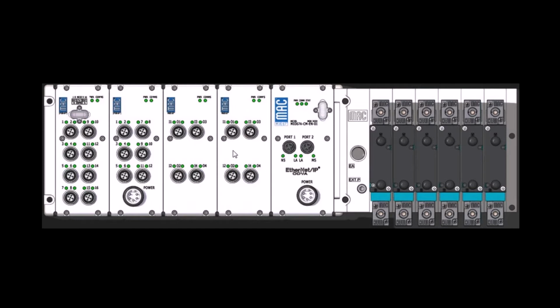Before we begin, we need to understand the physical layout of the particular analog current module that we will be working with. In our graphic here, we're going to be working with this module right here. This is module number 2, the second module from the left of the COM module. The COM module is located here. This is module number 1, which is an analog voltage module. Module number 2 is an analog current module installed here at this location. We will need to remember that this is module location number 2 when we configure our add-on instruction.